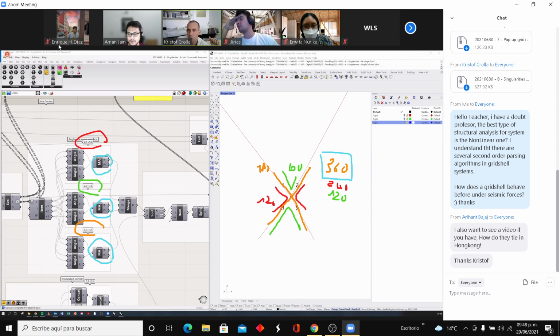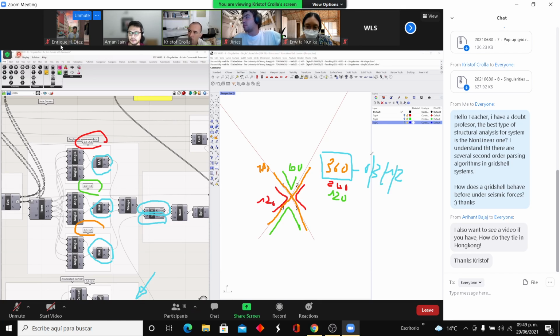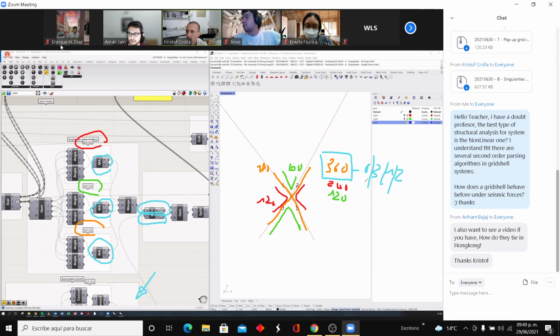So now I know what I want, but I now need to identify the two curves that come with it. I use a simple trick: here I'm sorting my data, but with it, I'm also sorting a text file. The text file I'm sorting with it is what I've circled around here, 0, 1, 2, 3, 0, 2, 1, 3, 0, 3, 1, 2. That's a little text file that I've produced underneath here. So by getting the first item of my text file, I'm actually selecting 0, 3, 1, 2. With that information, I can just split it up and select curve 0 and curve 3 and join them, curve 1 and curve 2 and join them. Does that make sense?